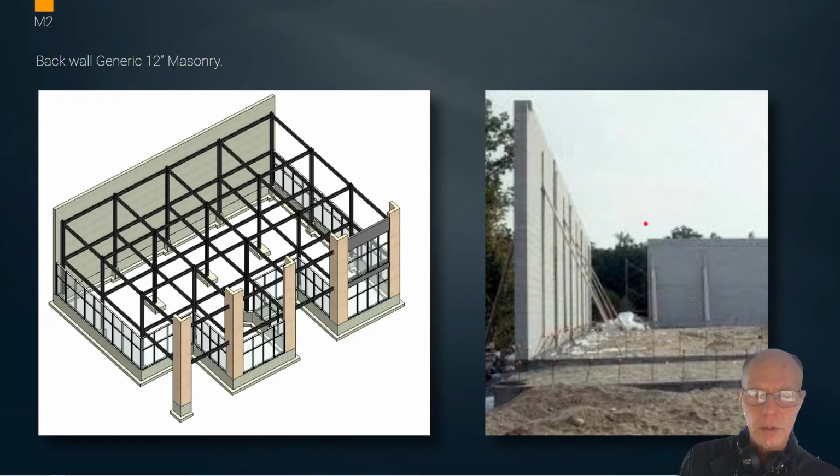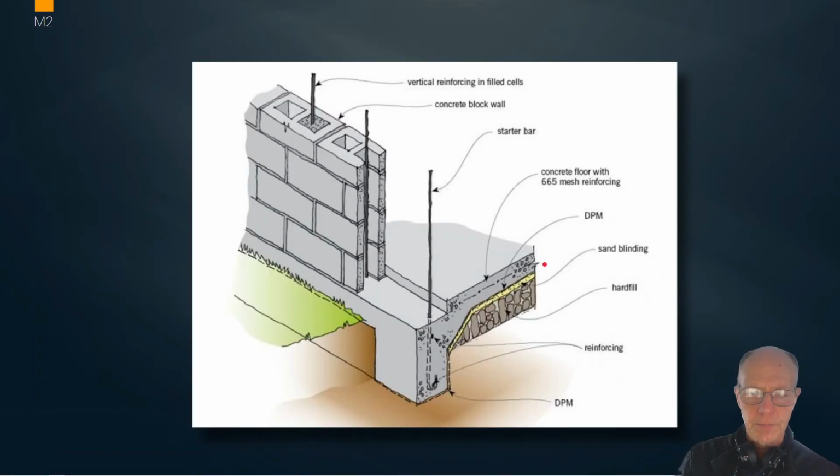So here's an example of that same start of that wall construction with the CMUs. We put a whole back wall up like that. We don't make a point out of showing how these are connected to the steel, but they would need to be in order to support it. So here's that typical wall now constructed vertically. And you'll notice that they have supports on both sides of it because it hasn't been structurally stabilized by what would be the attachment of the steel and the floor decks yet. So this is under construction.